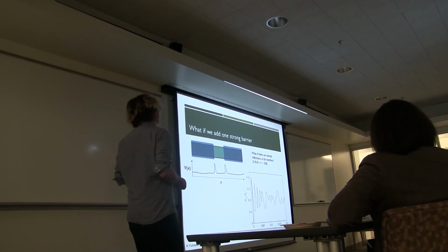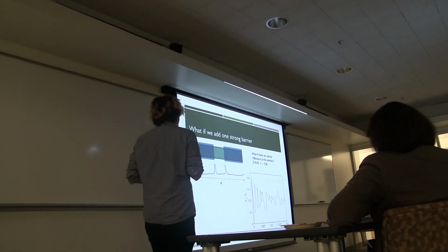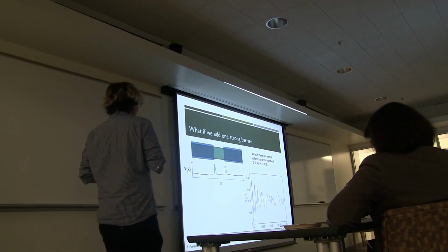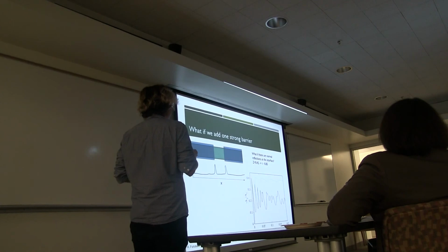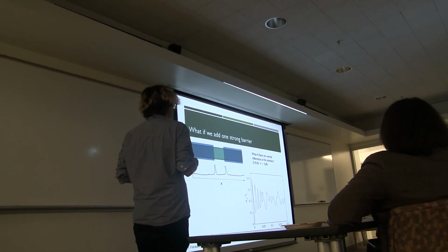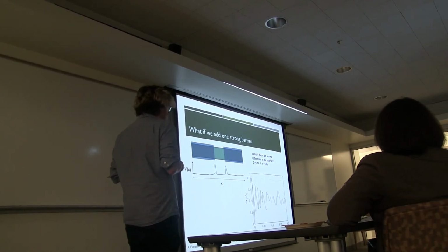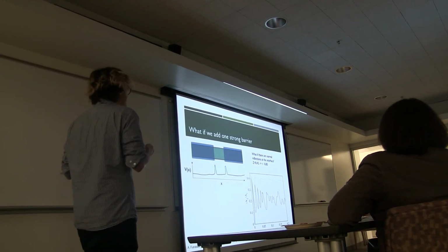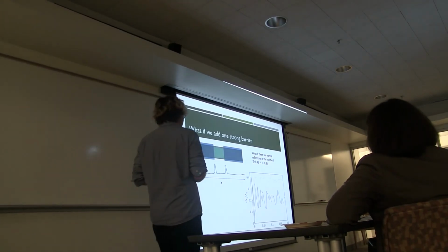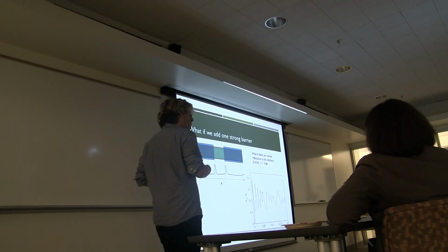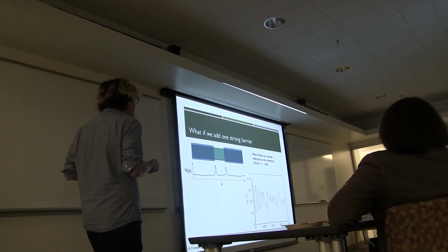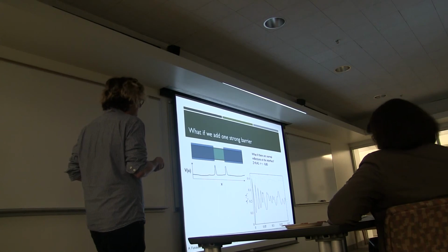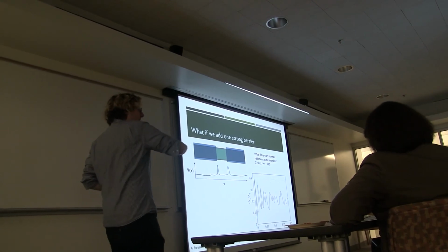So what happens if we add reflections at the interface? The way that we do that is by putting delta function potentials at the SN interface. I've chosen an interface transparency, corresponding to a transmission of about 0.85, which gives roughly the same shape that we observed in the measurements. And what we see already is there's a lot more structure to the shape of the current phase relation. We see a lot of peaks and valleys, and as you add more and more modes, it gets more complicated and the amplitude of the fluctuation falls.